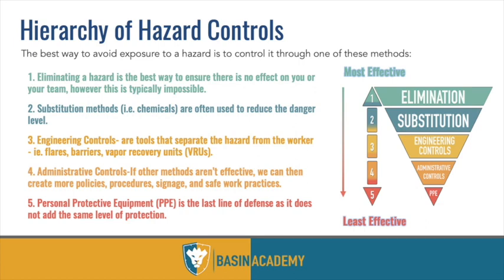For us, we found that through chemical treatment, through different safe work practices, where you stand, how you stand, where you direct the flow, do we vent, flare, different pressurized systems, different tools you can use subsurface, there are different ways to protect yourself. So that's kind of where I lean and the industry leans, and those are the best ways to protect yourself. PPE being the least effective method of protecting yourself.